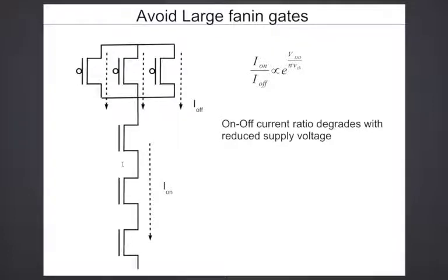But it turns out that it might not be a very efficient way to use just NAND2 gates in terms of area and speed. There is a case to be made for more complex gates. You can always cascade a bunch of NAND2 gates to get a more complex Boolean function, but you can build a monolithic Boolean function by creating the switching network for the pull down and the pull up in the same gate. So that is a monolithic gate.